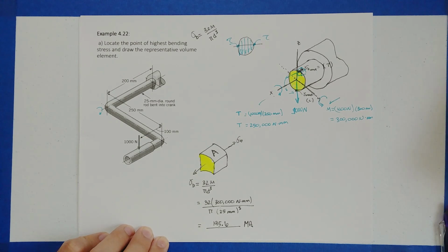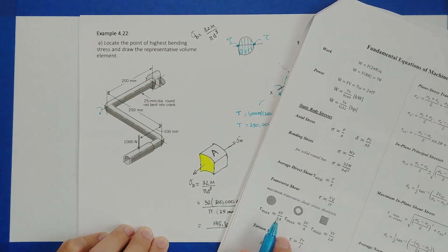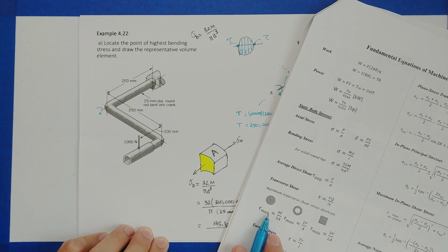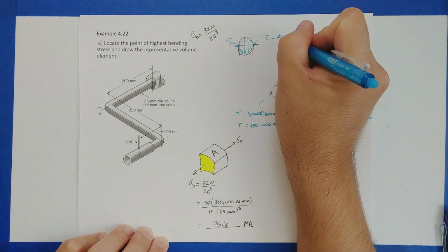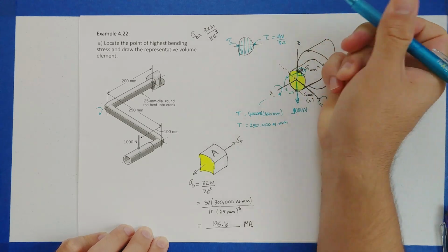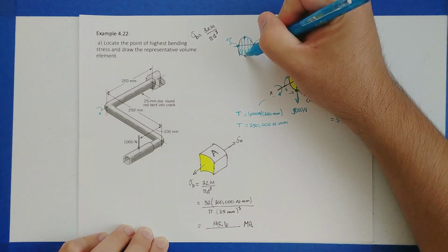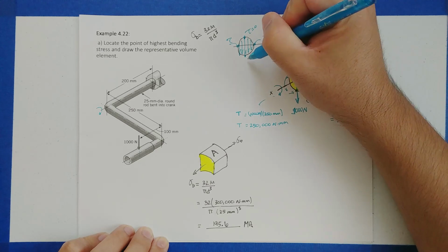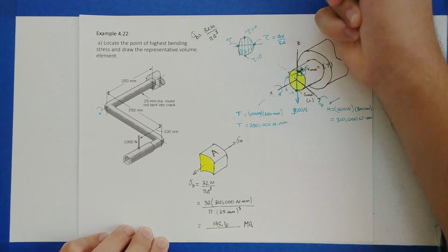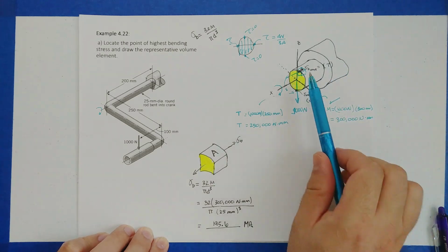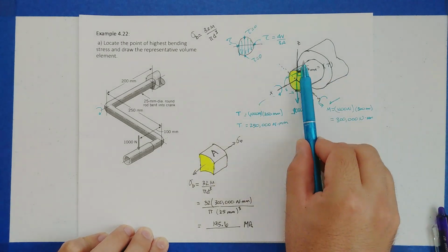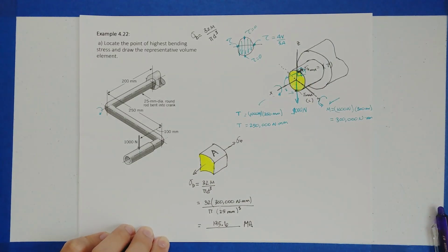What is that value? Well, from our equation book, we have our shortcut formula. It's 4V divided by 3A. So this would be equal to 4V by 3A. And at the bottom, tau equals 0. We cannot develop a transverse shear stress. So it means over here we got nothing going up and down, again because of transverse shear. But that's not the only thing we have, right?